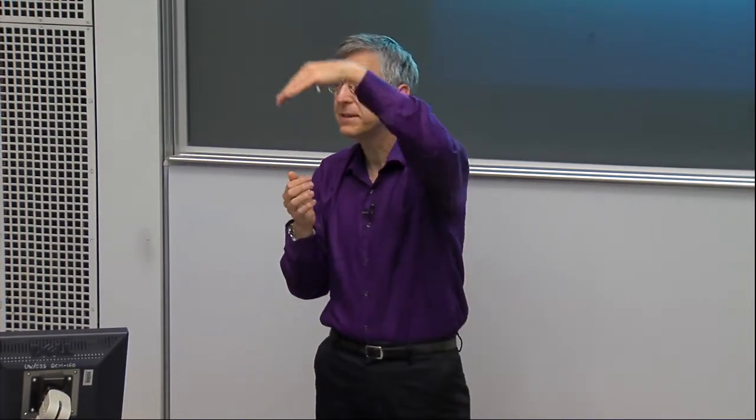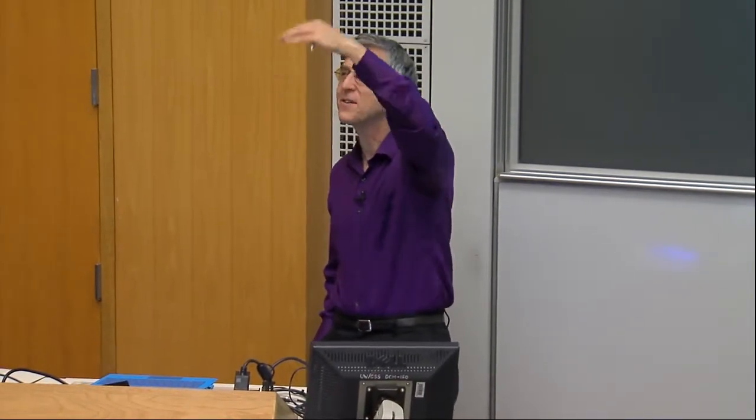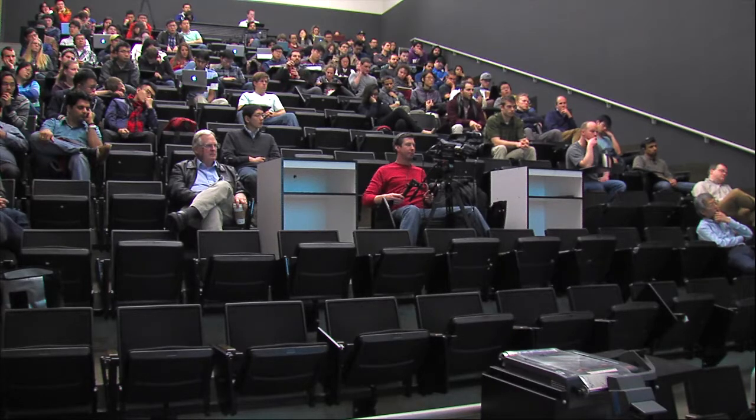The difference is that when I model an amplifier, I'm not modeling all the stages of the amplifier. I'm building a linear model of it, which maybe has some distortion in it. So I'm doing block modeling, and my time steps are not the time steps you're thinking about in a SPICE-like simulator. My time steps are just what I need so my output waveform has some acceptable error. We can show you examples. For RF circuits, the most important thing is you don't model the carrier. The carrier is the carrier, but you don't have events to generate the carrier waveform. Does this make sense?